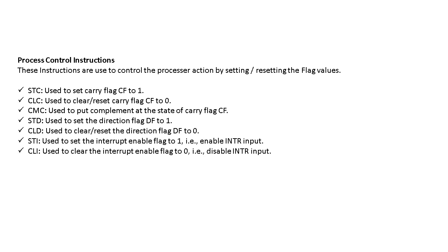CLD, used to clear or reset the direction flag, that is DF, to 0. STI, used to set the interrupt enable flag to 1, that is enable INTR input. CLI, used to clear the interrupt enable flag to 0, that is disable INTR input.